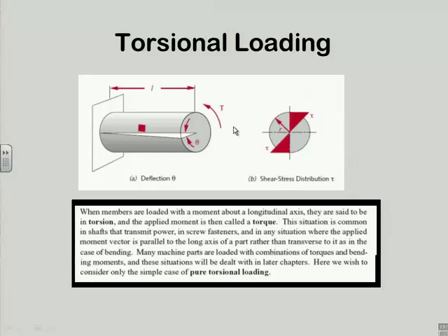So here you see what I just demonstrated. Here it's buried in the wall, so I have essentially a cantilevered shaft, and I'm putting a torque on the end of it. And I'm getting a distribution of stress, tau, which looks much like the bending stress distribution, with one big difference, and that is this is all shear. To picture this being shear, I think you followed my paper example very well for shear in a beam. Yeah? You can see those sheets slipping on one another.